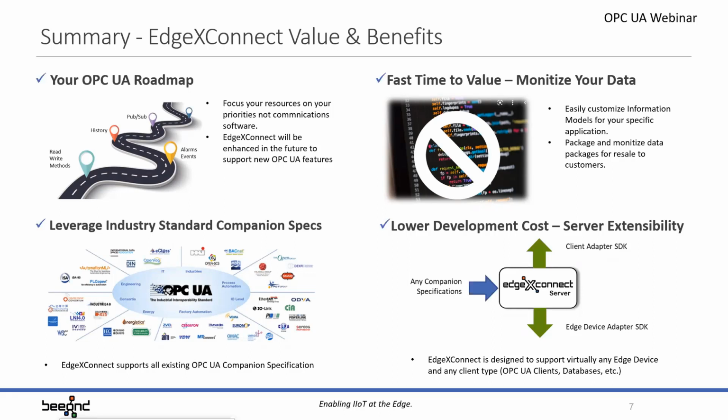We don't advertise that too much at this point, because OPC UA is the standard that's available today out of the box, but we do intend to expand in that area, adding other northbound data interfaces like MQTT in the future. So the product will evolve, but it gives you a good start with OPC UA.